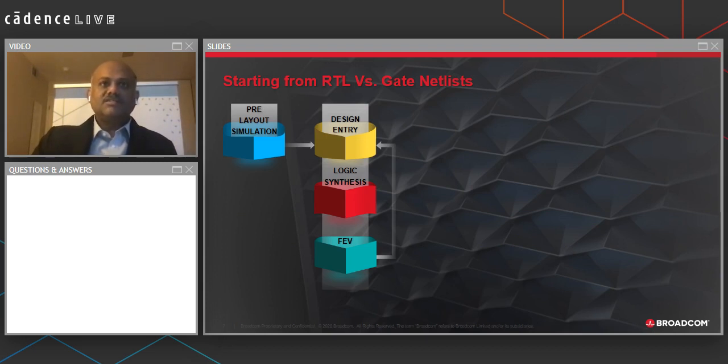So here are the early stages of ASIC flow. Basically, the design intent is captured as a HDL in design interface. It is verified during pre-layout simulation and declared golden. The golden RTL is synthesized and output netlist equivalence is formally compared against the golden RTL.